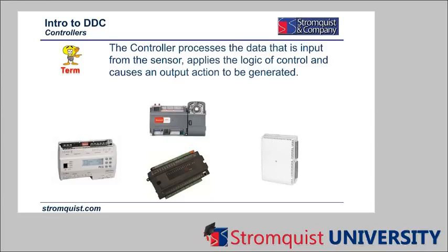Give you a few examples of what this is. So this is a Honeywell Spider. Anybody want to take a wild guess as to what kind of equipment that controller would go on? You got it. Go ahead. PIU, VAV, PIU. You got it. So what we have is an onboard actuator right on that controller. So you wire it up with your terminals here and here, and then that goes right over the damper shaft that's sticking out of the PIU or the VAV box, and everything's controlled right there.